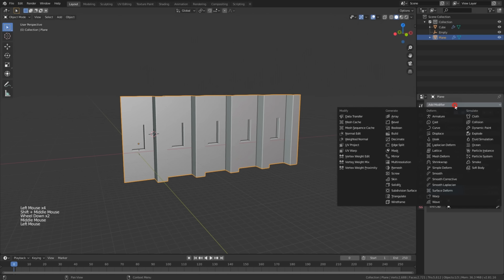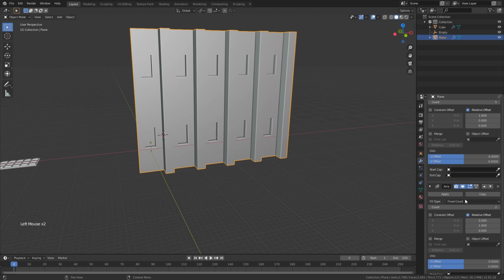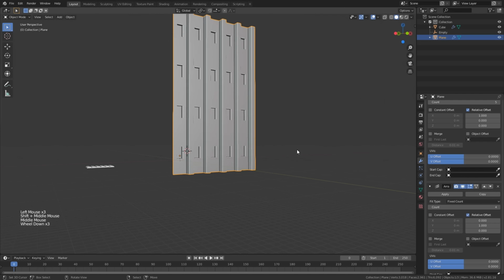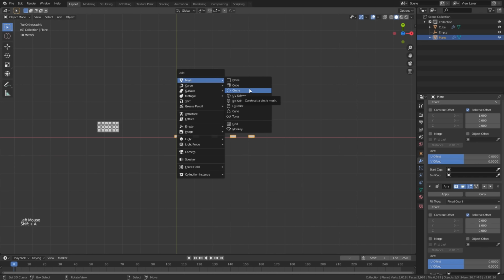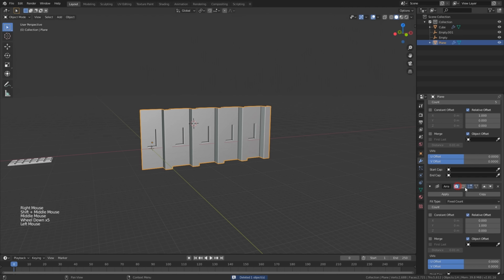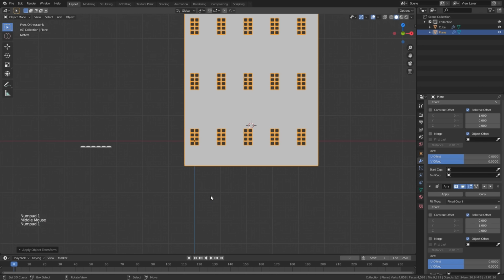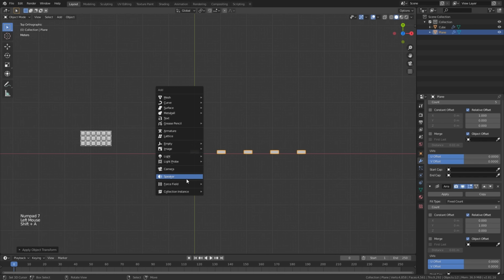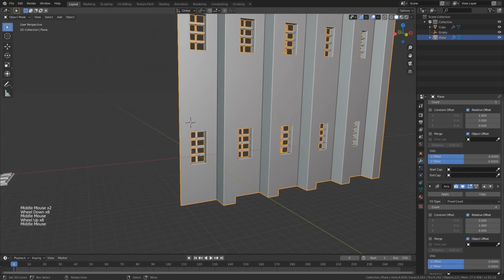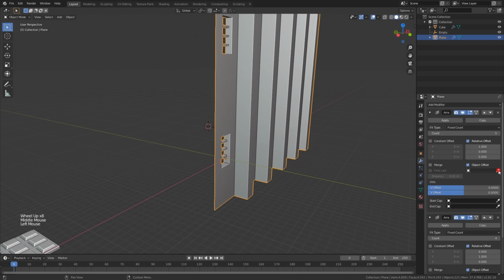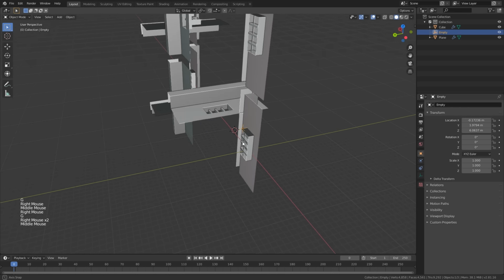Now imagine if I add one more array modifier, and instead of just like before, I use vertical duplicates. Also, if I go to the top view and bring one empty object over here, let's see if I can modify this further. I'll create one empty object over here, plane axis. Now in the first array modifier, I'll select this one as a driver, I mean for transformation.